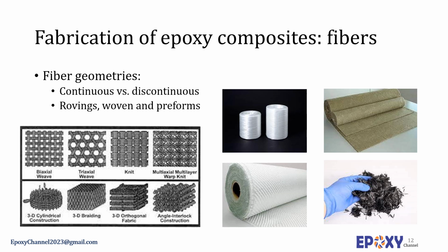The woven cloth can take on several forms: unidirectional, plain, satin, triaxial, hybrid fiber fabric, or woven tape. The fabrication of fiber composites with epoxy resins is dominated by those involving continuous fibers: lamination in an autoclave, pultrusion, filament winding, and hot compression molding.